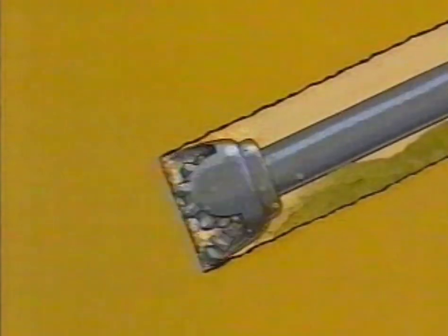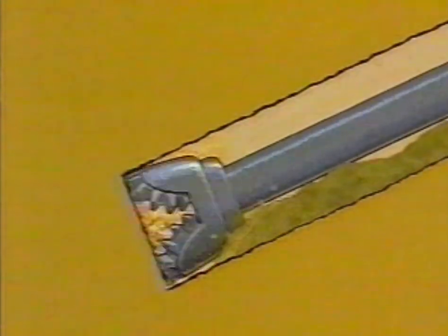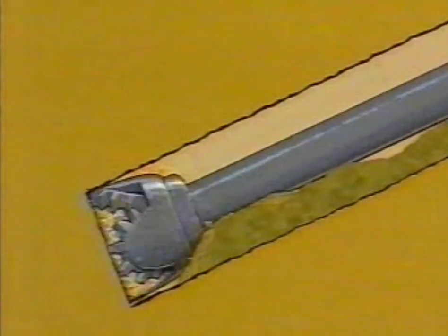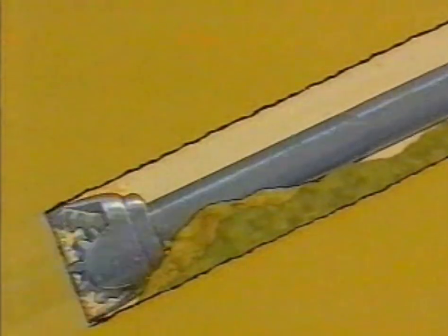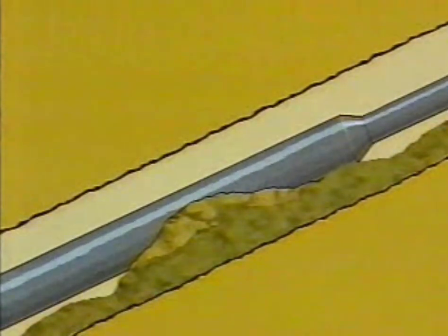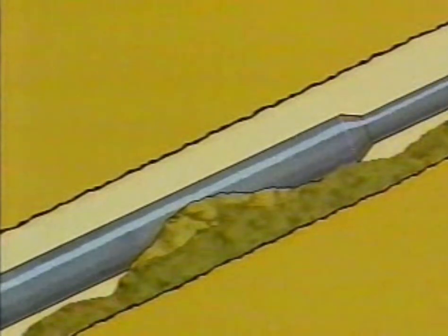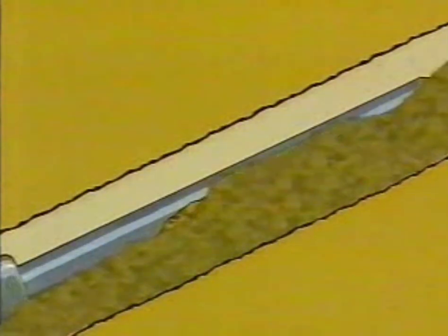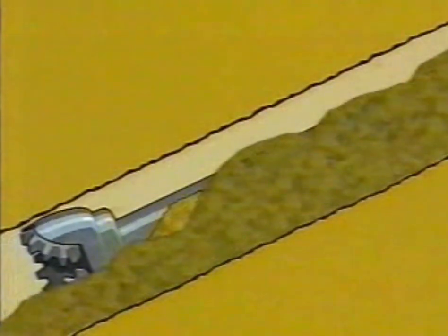Generally speaking, poor hole cleaning results in overloading the annulus, but in deviated wells, it also results in the formation of cutting beds on the low side of the hole, especially when the hole angle is between 45 and 70 degrees. The cuttings may migrate slowly up the hole in a manner similar to sand dunes, and when tripping out, they may pack off behind the drill string, causing it to jam.